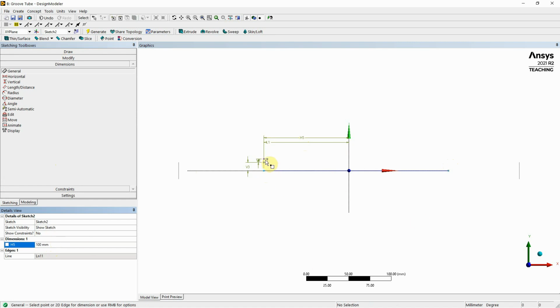Now remember, this spiral groove is going to go along this path and it needs to end here with this side being here. So we know that this is 4, so this can't be 100, because if it's 100, the spiral groove will be past the 200 mark. So we want to make sure that this ends 4 millimeters less. So here, give it a dimension, Control Z.